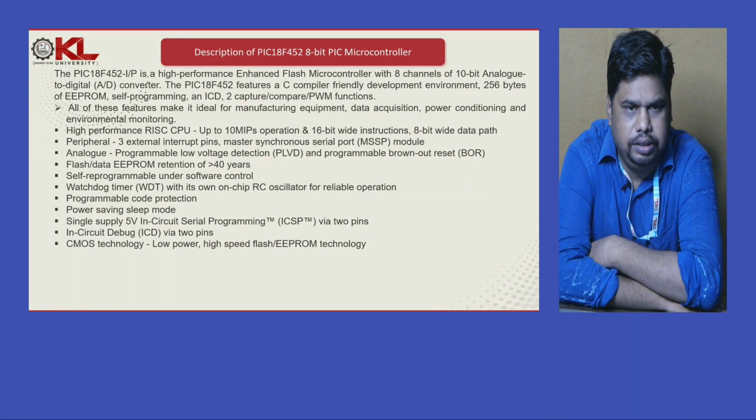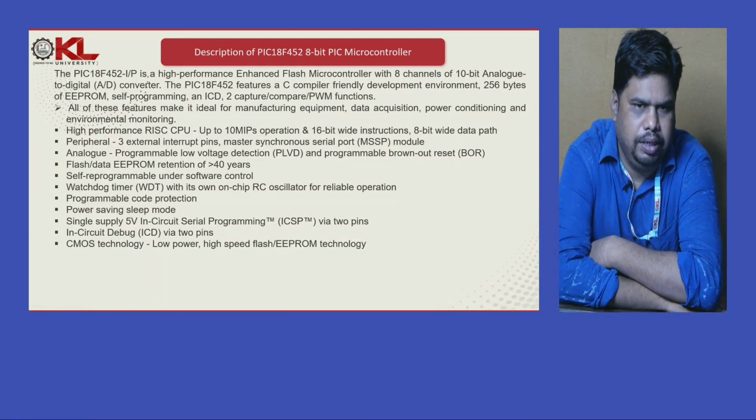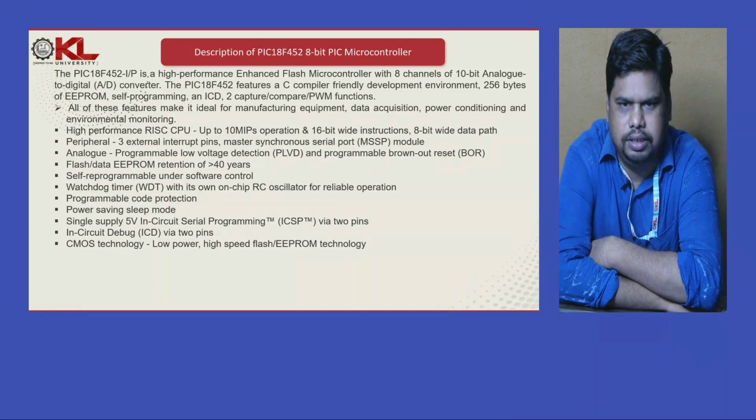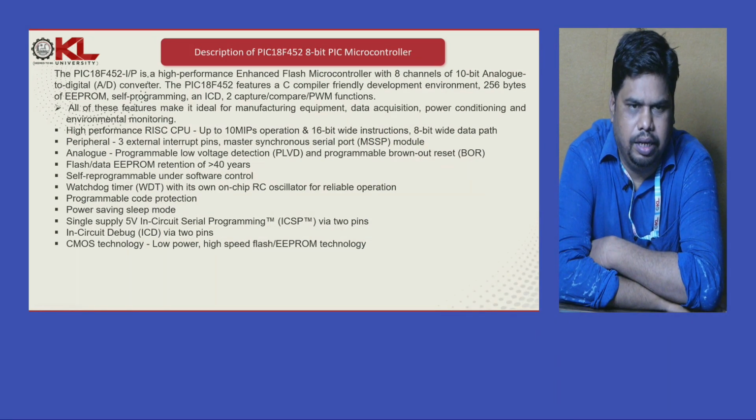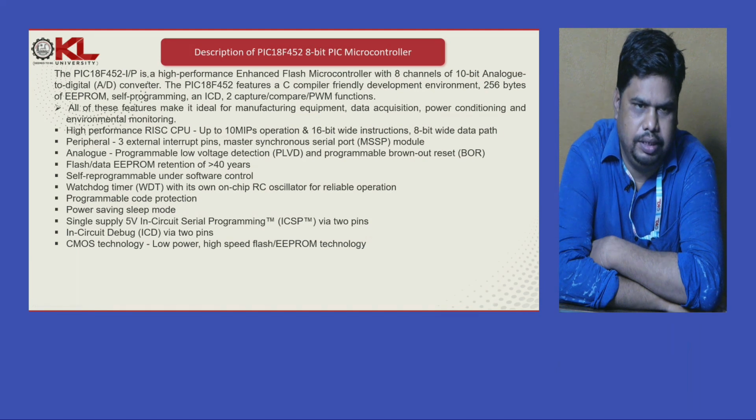So it's a high performance RISC CPU, up to 10 million instructions per second operation, with 16-bit wide instructions, an 8-bit wide data bus, and it has 3 external interrupt pins. Master synchronous serial port module is there. Then it has PLVD, programmable low voltage detection, and programmable brownout reset facilities are there.